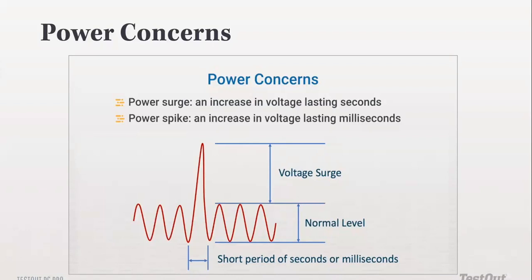It went below the normal level. Let's say it goes below the 10 volts that we have as normal. If it leaves 10 and goes to like 5 or 3 volts, we refer to that as a sag, a power sag, S-A-G. You might know of that as low voltage. A lot of you might already be referring to that commonly as low voltage, where the required voltage is not arriving, but it is coming in a lower intensity.